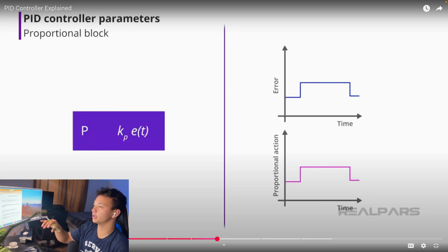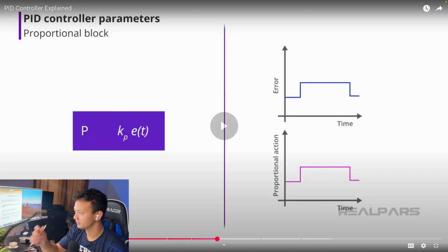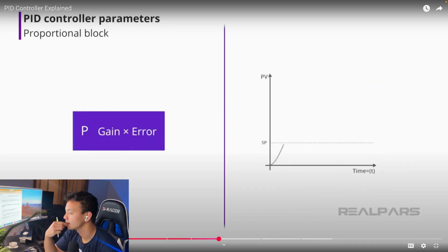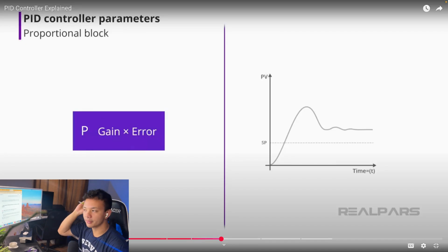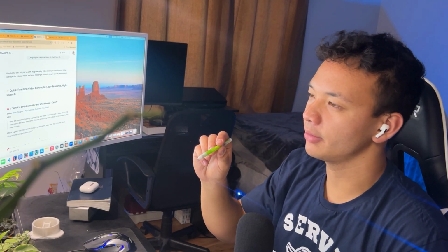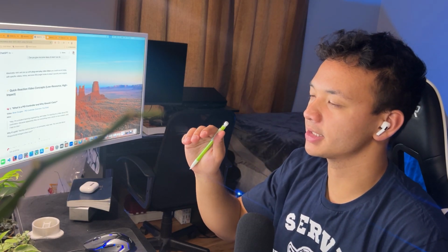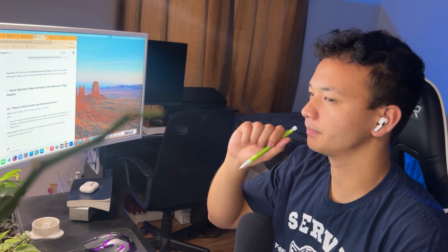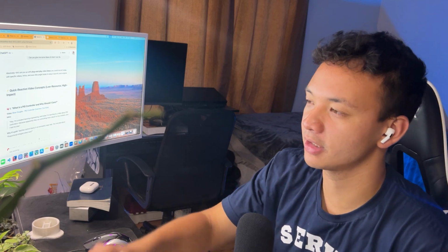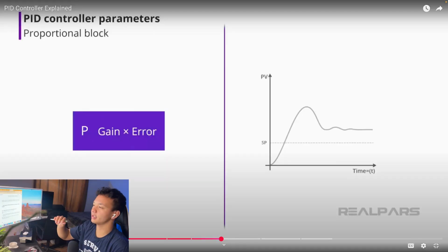So it might not be the same value, but it should follow the same, what is it called? The same pattern, word. Anyway, you understand what I'm saying. Unfortunately, the closer you get to the set point, the less it pushes. Okay, so the problem is though, because it's proportional, once the error is 0, the set point is not going to be 0. From what I understand, from the calculations, it might have the same shape, but it might not be at the same level where the set point is.